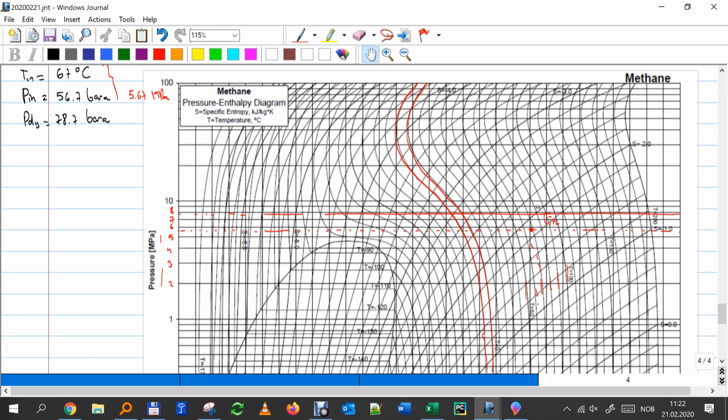And in this chart it is very nice. You also have entropy lines. You see S, these are the lines that go in this direction. S equals 0, S equals 1, S equals 2, and so forth. So for that point 1, what entropy do we have? If you go on this line, it is between -2 and -1, so you have -1.2, -1.4, -1.6, -1.8, -1.9. That's the entropy of that point. The entropy at inlet 1 will be -1.9.